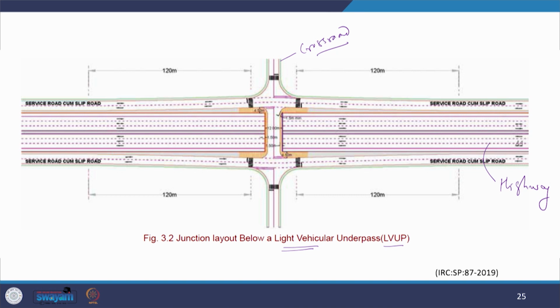Now, if you see the design, because the vehicles are smaller in size, the corner radii are not big, they are smaller in terms of the R value, and there is a possibility for these smaller values even to take a turn at 90 degrees. So, what you can see is that the vehicle coming from this direction has to go in this form, or the vehicle which is coming straight and then goes straight, these possibilities are there.